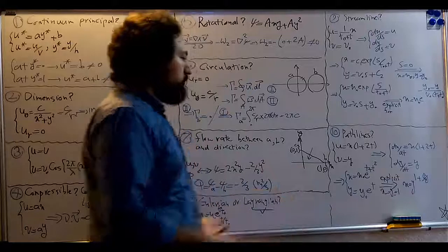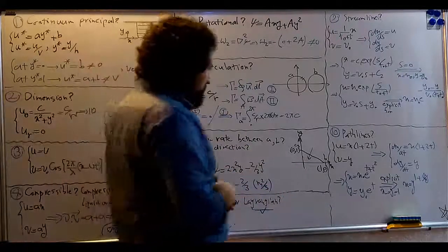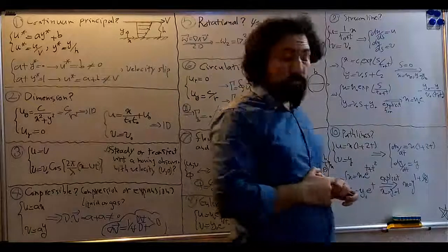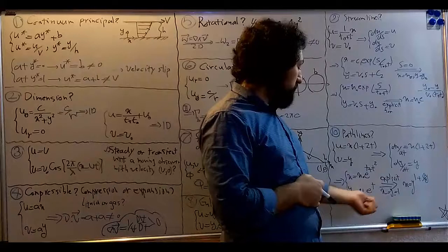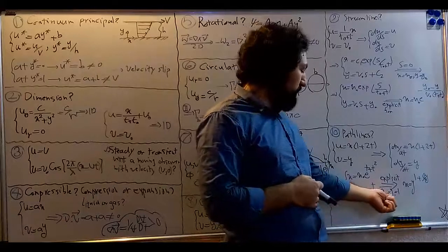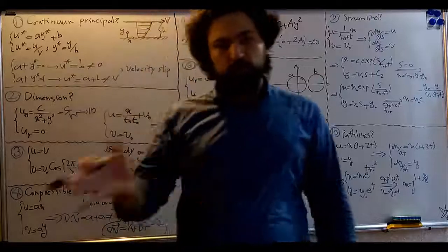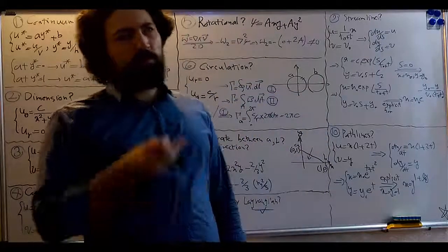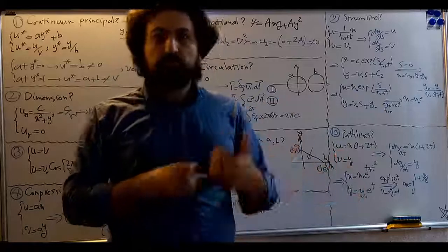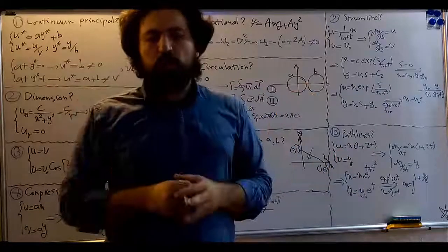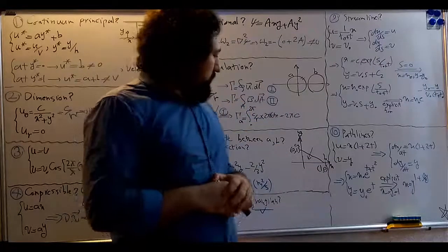So again, integrate, but this time with respect to time, and substitute the boundary condition, which is the point x sub 0 and y sub 0 equals 1 at the initial time. So this is the path line of the particle which starts its motion at the initial time, or t sub 0, at point 1 and 1.